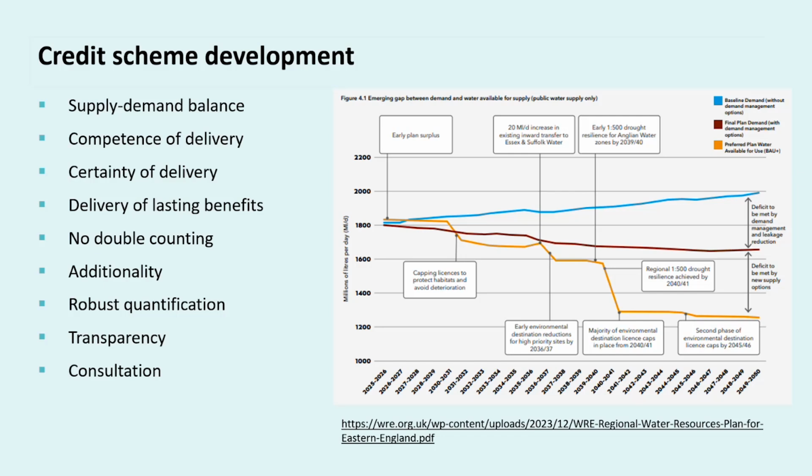And so pre and post implementation water meter readings will be required to confirm the reductions in water use. And care needs to be taken to ensure that those aren't skewed by being taken on either side of a seasonal change, maybe from a dry spring to a wet summer, which could skew the data.